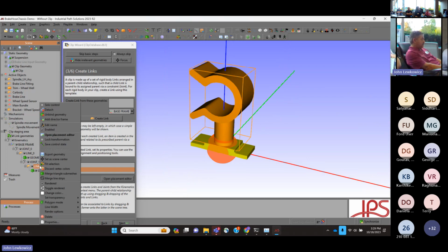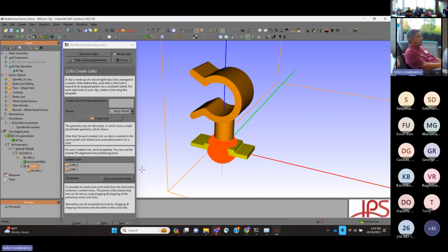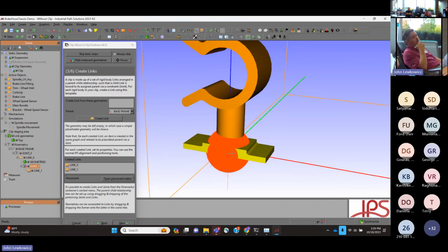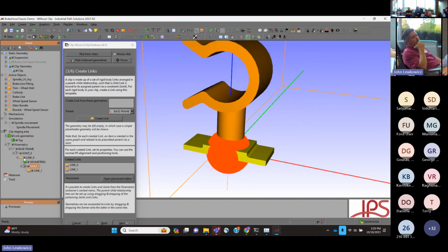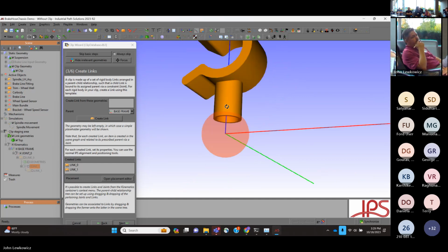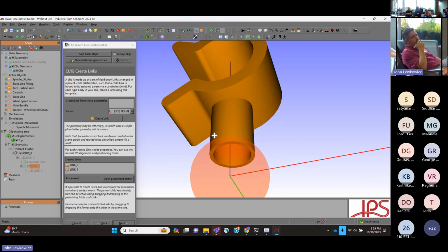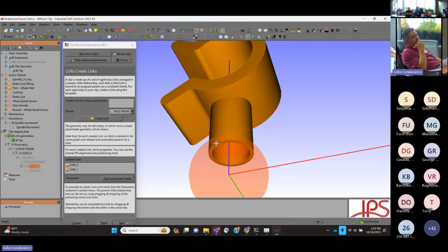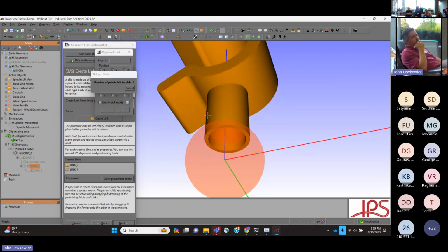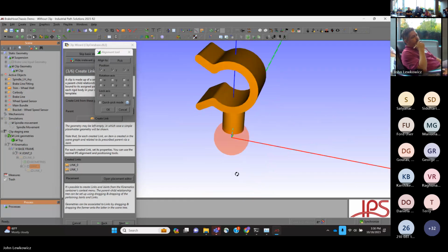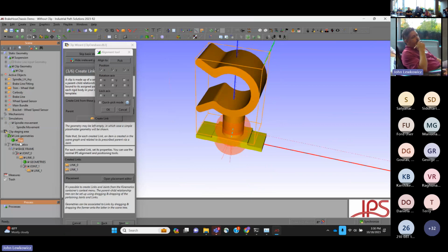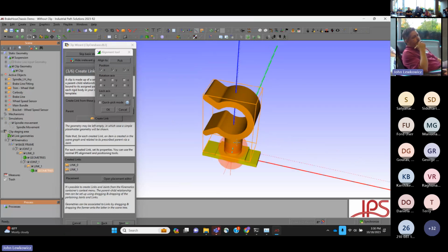And then if I want this to move properly, I've just got to relocate this joint so that it's on the correct center line for this upper portion, right? Because I want it to move about this central axis. So I'll just pick a circle here, hit OK, and then I'll add this back into here. Next,